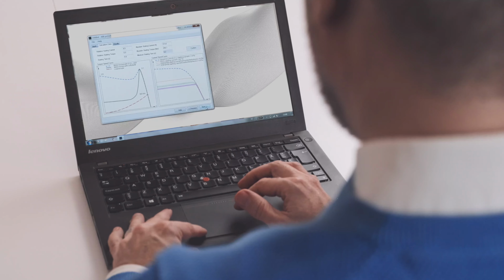So that was the Data tab. Let us look at the key takeaways. Higher starting current will give you more torque and shorter starting time. Now we know how to apply the minimum starting current for a customer application and also know the approximate starting time. The motor torque curve for the Softstarter shouldn't at any given time be lower than the load curve. Now we have modified the information under the Calculation tab. Let us hit Next to get to the Result tab.